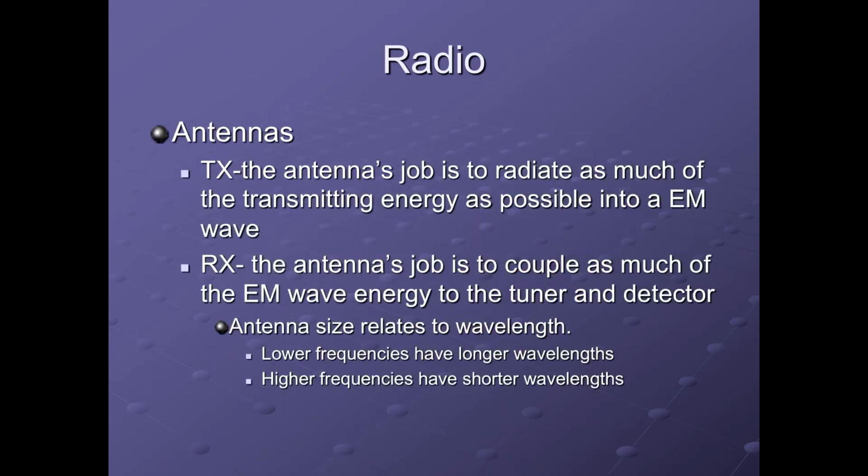So the main thing we want to point out is that antennas and all the antenna gear have everything to do with wavelength. The lower frequency, which has a longer wavelength, is going to have a bigger antenna, a bigger duplexer, a bigger resonator. Anything that has to do with the actual RF signal itself is going to be physically bigger for longer wavelengths or lower frequencies. I made that mistake myself on my first job, which I spec'd out for a mountaintop repeater. I didn't take into consideration it had to go into a very small shelter, and I engineered the whole thing for a lower VHF frequency.